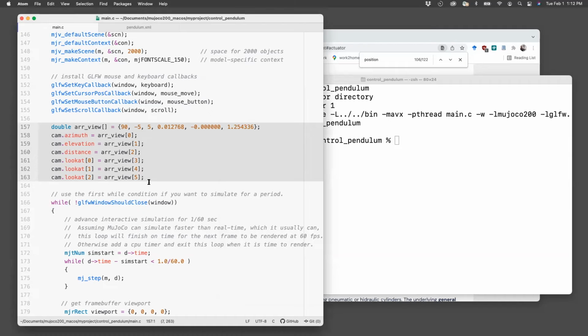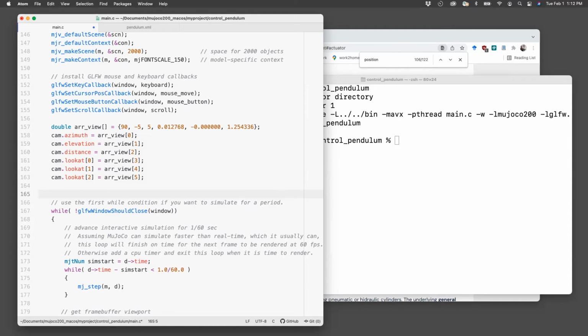So what we can do in that case is we can set the initial position by doing this, which we discussed in the projectile class. So the Q pose basically gives me the initial position of all the degrees of freedom. So in this case, there's only 1 degree of freedom, which is the pin joint. And so there's nothing to think about, just should be 0 equals some value.